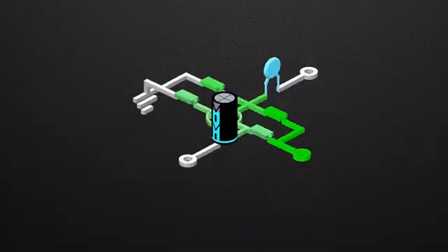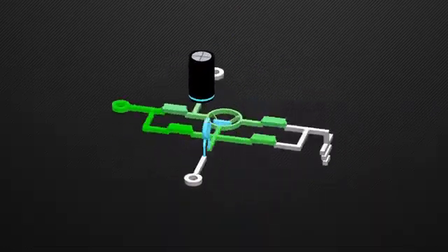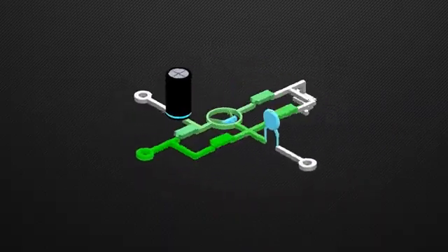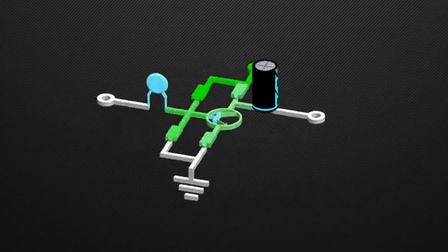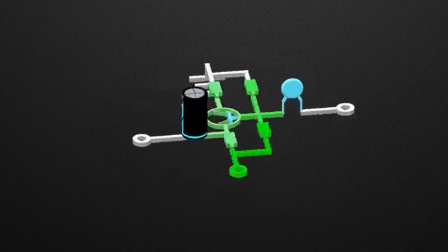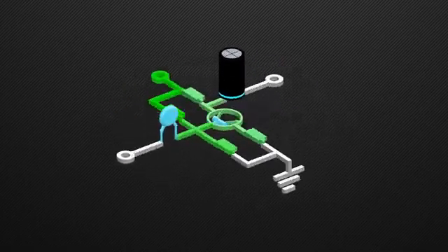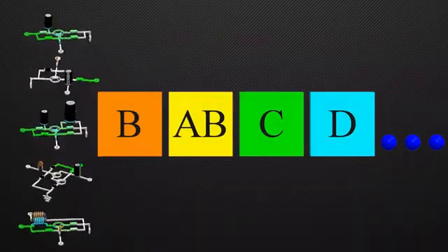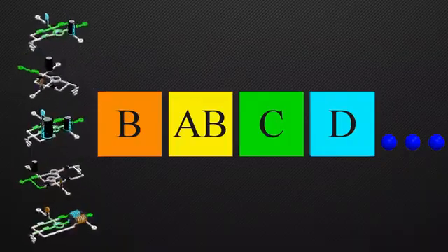A Class A amplifier can reproduce full waveform, with very low distortions, but as the transistor is biased, it's always on. This and some other factors reduce its efficiency to less than 30%, which is very low. Now you know how a Class A amplifier works. In the upcoming videos, we will explore the remaining classes of amplifiers.